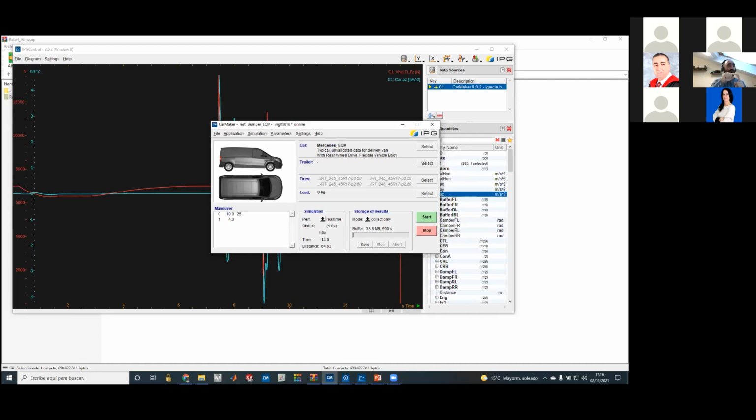If, for example, I measure a phenomenon that lasts 2 seconds, the RMS value of that phenomenon will be less than a phenomenon lasting a higher period of time. So the vibration dose value gives us the capability to compare 2 different signals.